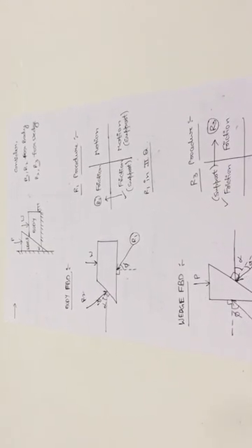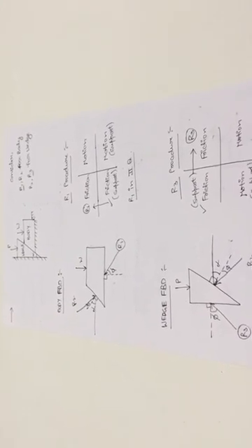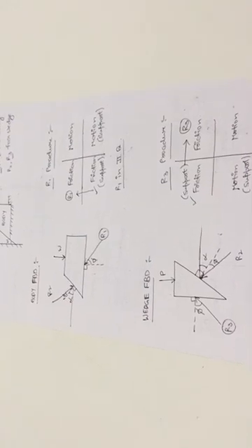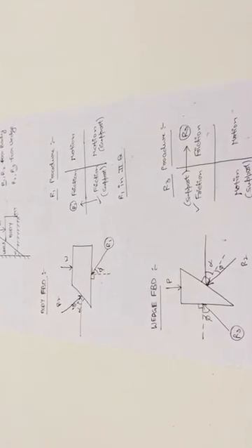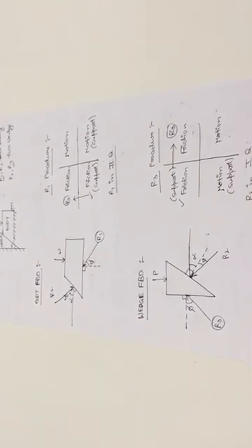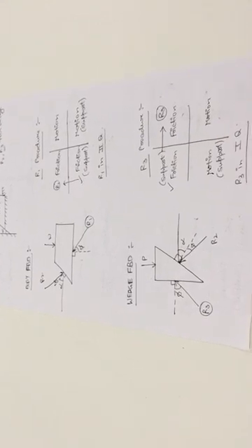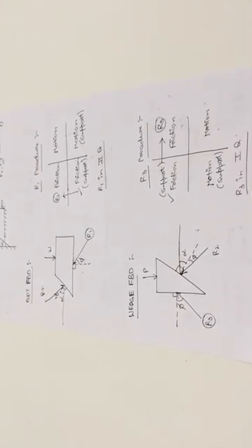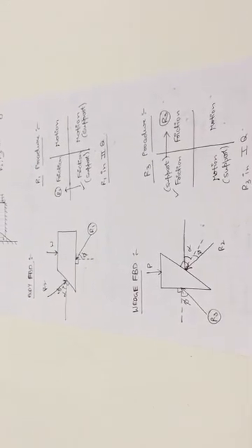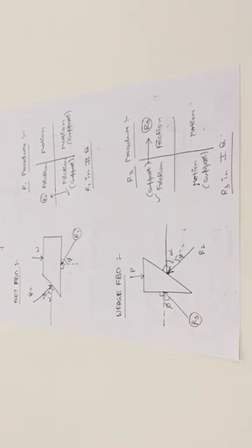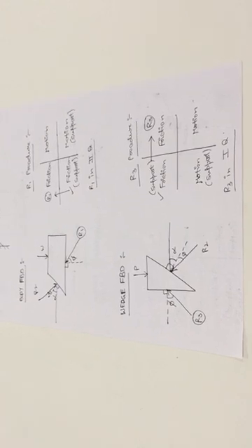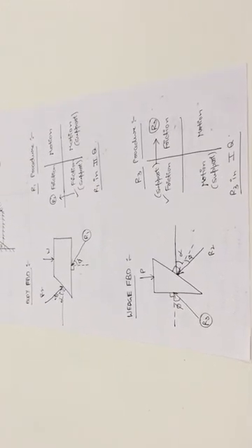But for R1 and R3, you will get some confusion. Exactly in which quadrant support is there. So for that confusion, to get clarity, we will opt for some extra procedure. In that procedure you can know the exact support quadrant. So from that quadrant you can find in which quadrant the reaction force is acting. So from that extra procedure for R1 and R3 you can calculate the reaction forces. And one more thing, when you are doing that extra procedure for R1 and R3, as R1 is coming from the body, see the motion of that body only. R3 is coming from the wedge, so see the motion of the wedge only. For whichever reaction force you are calculating with that extra procedure, see that body's free body diagram motion only.